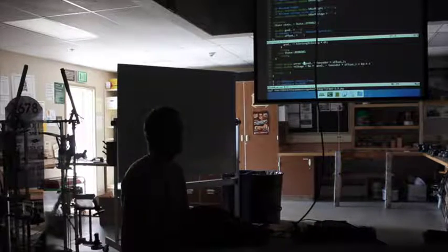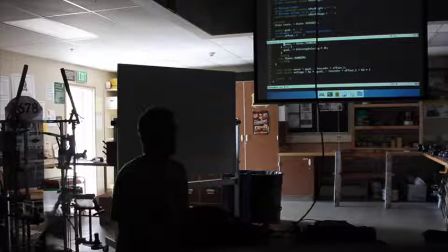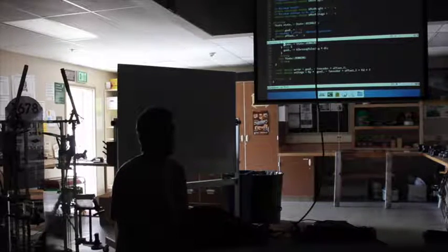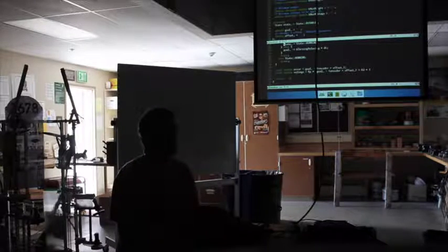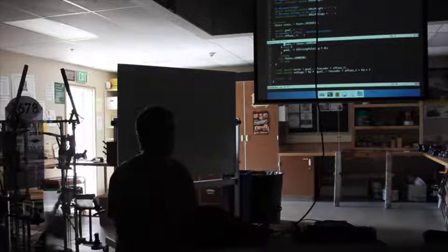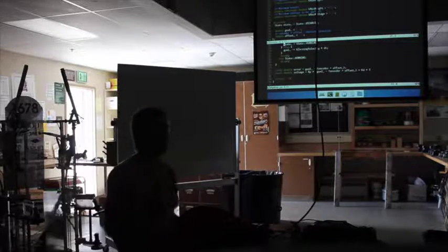Question. If this is velocity PID, why are we doing position PID for lowering? Well, in the end, we want to take the elevator to a position, right? Yeah, but while you're lowering, the only knowledge you have is that you're going down at constant velocity, right? Sure, but if we want to implement it that way, then we need to design a lowering control loop and an operating control loop. So if we can just use our operating control loop to do our lowering, we can save ourselves a lot of design work. So you can just generate a slowly moving system by telling it to go down a little bit each time. Yeah, and that works pretty well.